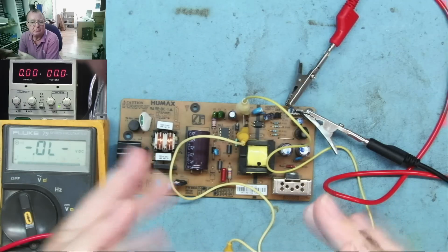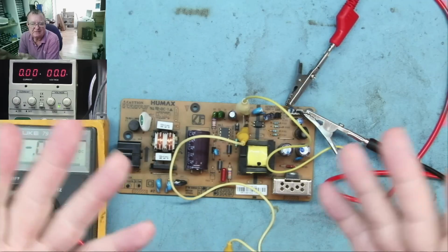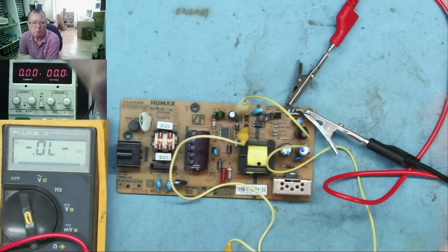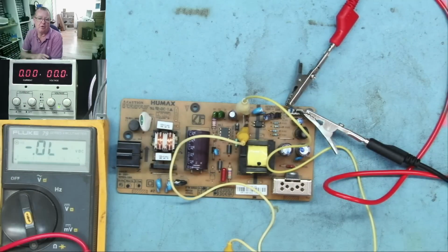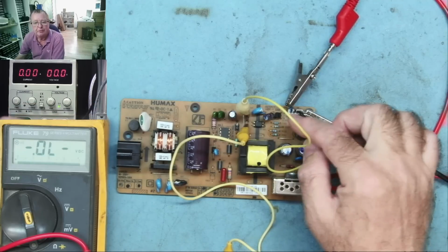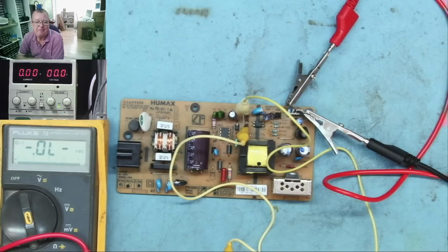Bear in mind, on some power supplies, such as ATX for example, the opto-isolator is only measuring one of the output rails or monitoring. On ATX, it's normally the 3.3 volt supply that is being monitored. But you do need to know, you need to be monitoring the correct supply. It's not difficult to work out if you're not sure if there's many outputs of a power supply. Just trace through the TL431, you'll be able to see it and figure out which voltage rail it's connecting to.